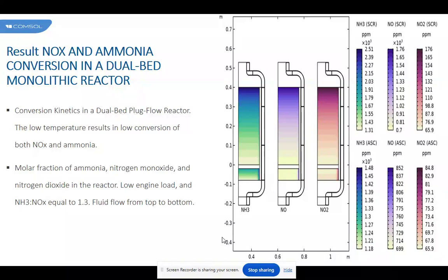However, the form of substrate is equally important. There are essentially three physical quantities that among them allow a complete description of the resulting converter. These are the cell density, the wall thickness, and the washcoat loading. The cell density is the measure of the number of channels that are present per unit frontal area, typically reported in cells per square inch.